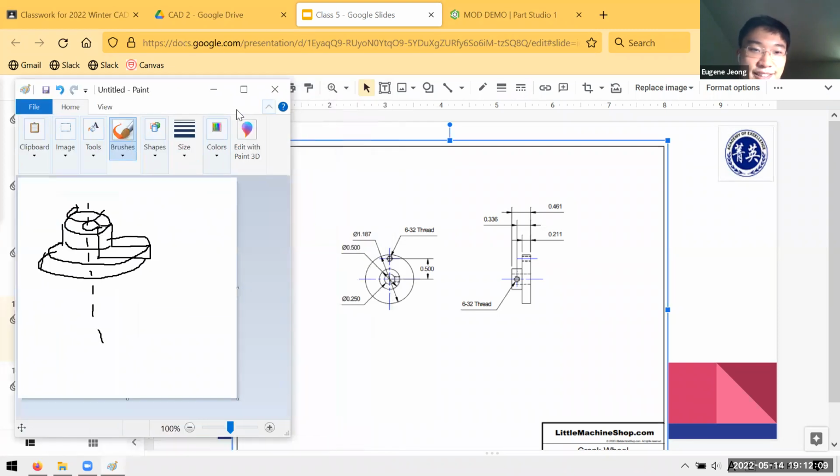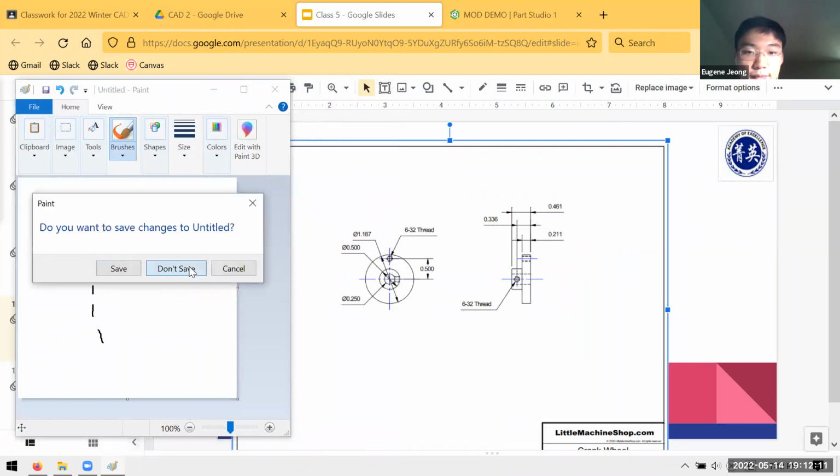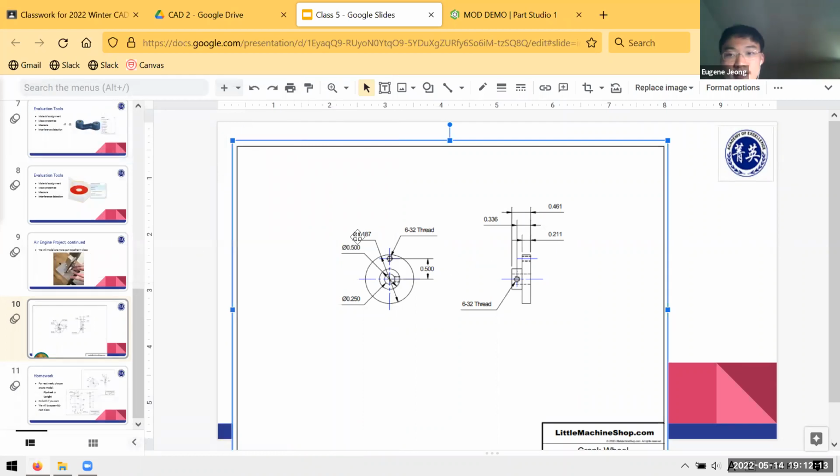All right, no more of my drawing. Either approach is fine. Using the revolve will reduce the number of features you have, since you get like a 3-for-1 deal. You get the hole through the center, the top cylinder, and the bottom cylinder all in one feature. That's a bonus. I guess it's easier to think about when you do it with extrusions. So it's up to you. Either approach is fine.